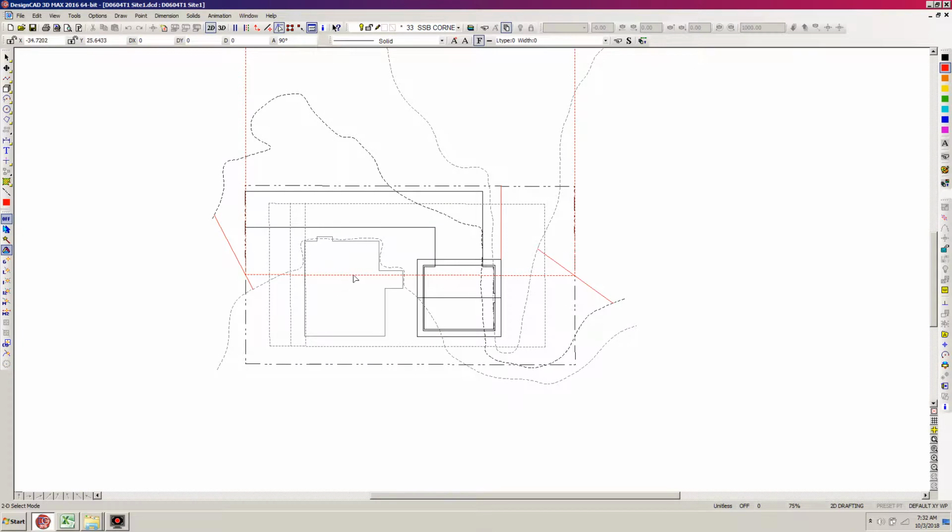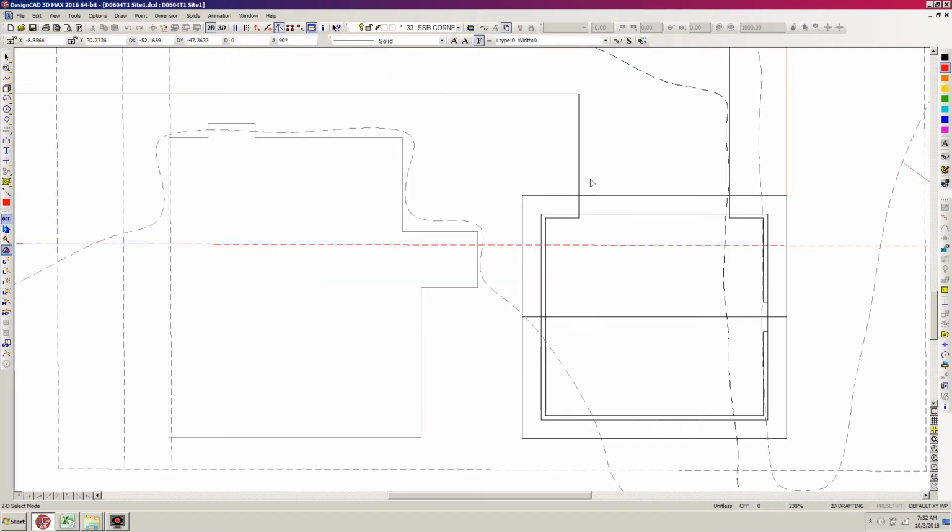And so this is the existing residence, and this is where the existing garage is, and the driveways come on out. It's an L-shaped drive, and it seems that the most logical place to place an exterior stair would be between the residence and the garage. There are some things that we need to consider there. I'm assuming that the stair will be non-combustible, a steel stair, powder-coated steel stair, at minimal maintenance and all of that. So I'm going to hit Z for zoom and zoom up on this area a little bit just to see what I have between the existing residence and existing garage, what that space is, and to make sure that I have enough room for a stair there.